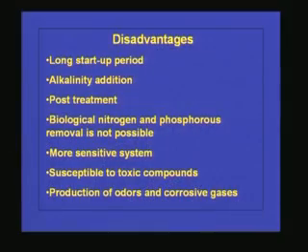But if the process is having so much of advantages, why is it not becoming so popular in our country or worldwide? So definitely there will be many disadvantages for this process. We will see what are the disadvantages of this anaerobic process. The major one is it requires a long startup period, and the second one is, because in the system a lot of acidity is produced, addition of alkalinity is very essential, and this process is not able to remove nutrients like phosphate and nitrate. So there is a requirement of post treatment.